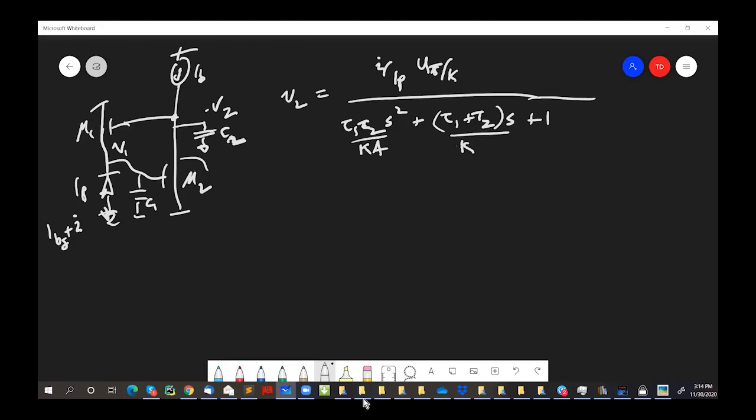The gain here is minus A, which is the early voltage of M2 over the, yeah, so it was something like that. Does this look familiar from last time? Do you remember how we calculated that transfer function? We basically just wrote down the small signal equations and then solved for V2 as a function of the small signal input current.